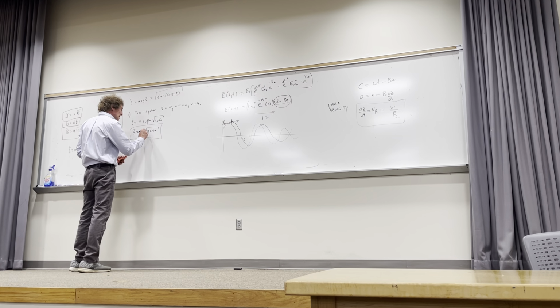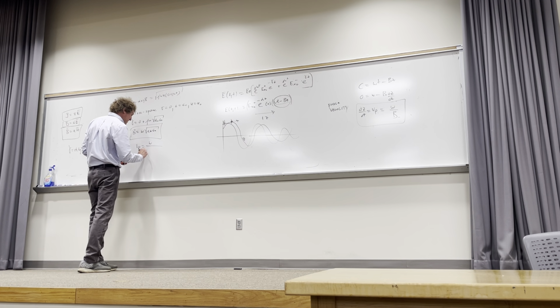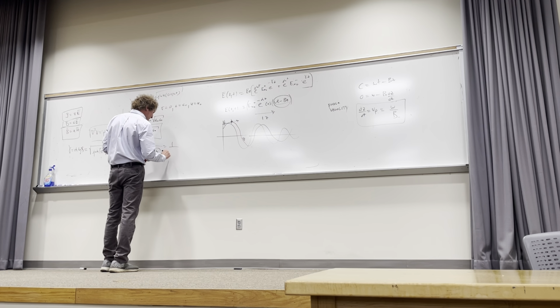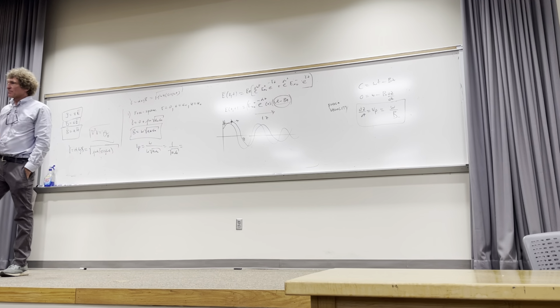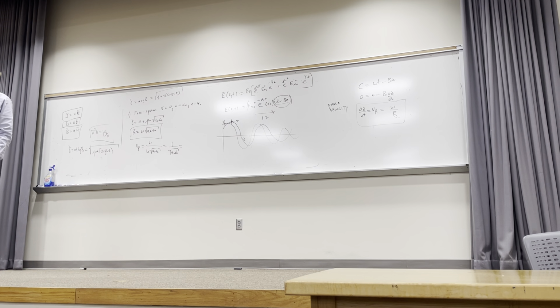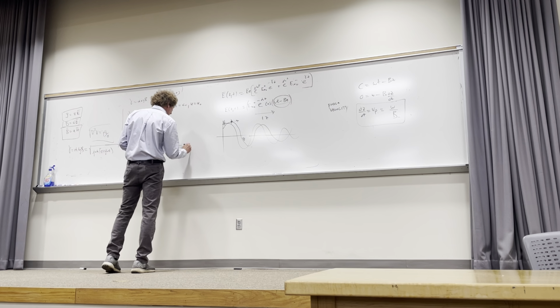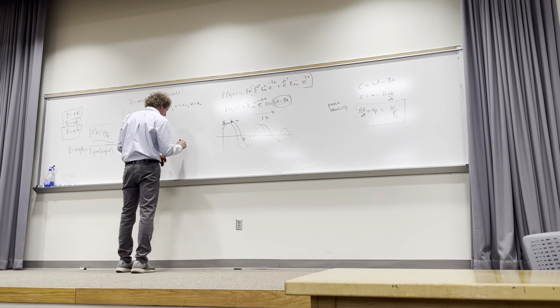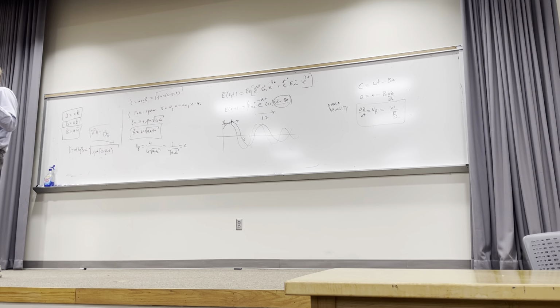Now, phase velocity is what? It's omega divided by beta, or omega divided by omega square root of mu naught epsilon naught. And this is a very famous fact. What is the 1 over the square root of mu naught epsilon naught from physics? It's the speed of light in a vacuum, right? In a vacuum. And normally we label that c. Well, it's about 3 times 10 to the 8th meters per second, slightly less than 2.99 something else.